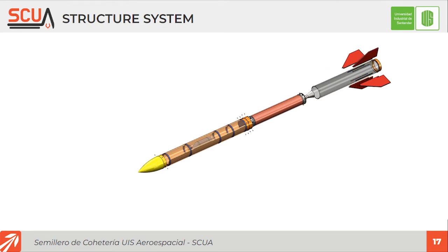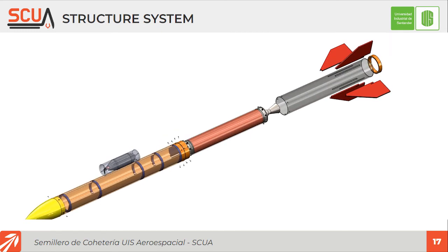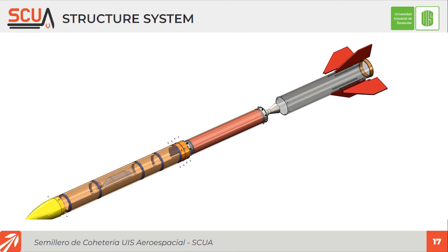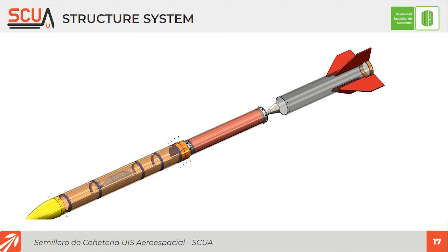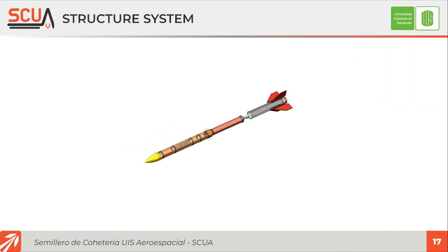Finally, the nose cone is going to be attached to the principal body frame using nylon fasteners, which will be broken by the expulsion system using a force of 250 newtons. This would be a critical point of the design of the expulsion system. All the design is themed for additive manufacturing, using metal reinforcement in the critical structural parts of the frame. In that way, we can reduce weight and material cost of the rocket.